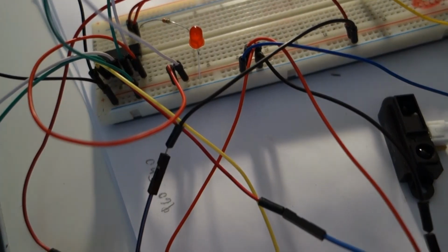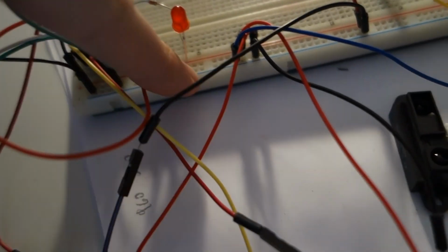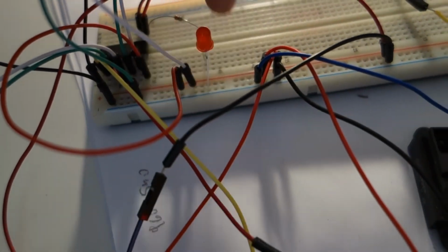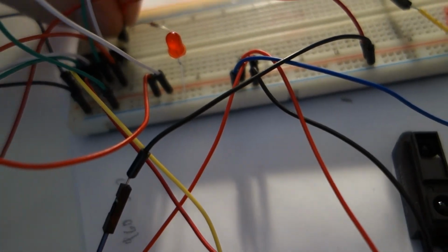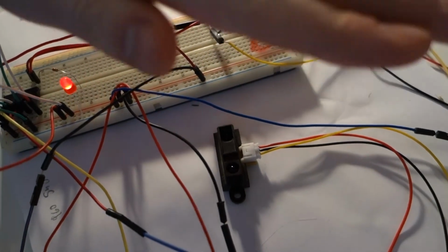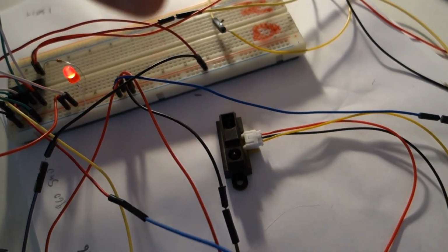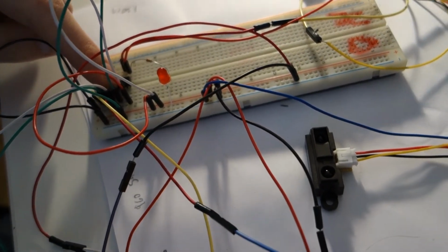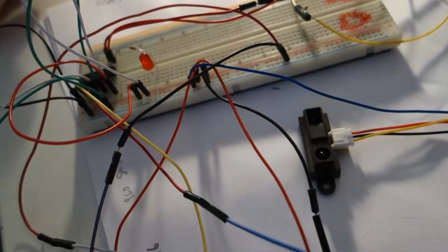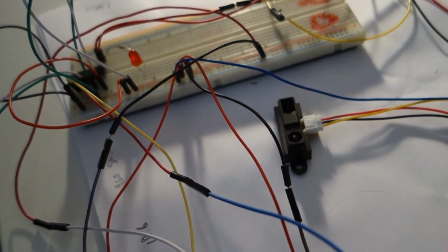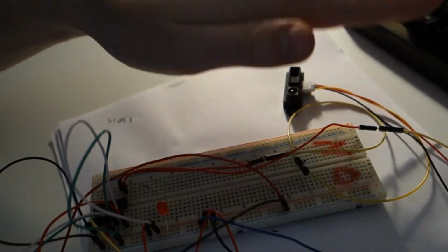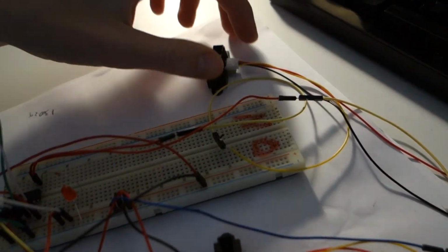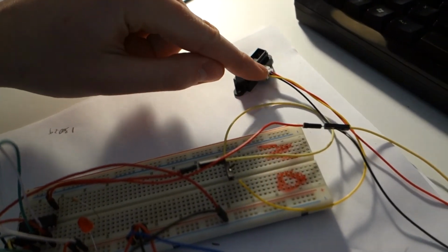If something doesn't work for you, try to debug the circuit, and if you have a resistor and an LED, you're set. This LED's shorter leg is connected to the negative rail, to the ground, and the longer leg is connected through the resistor to the distance detector. When this happens, it means that the detector works correctly, and the issue is somewhere in the wiring here or in the code that initializes the SPI connection. However, if you wave the hand over the detector and the LED doesn't work, then your issue is probably in supplying power to the detector.